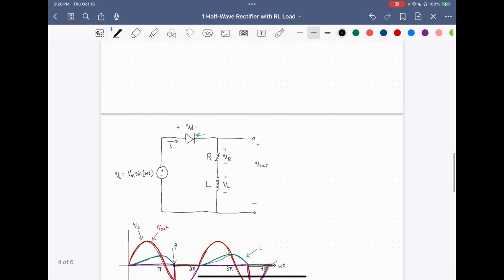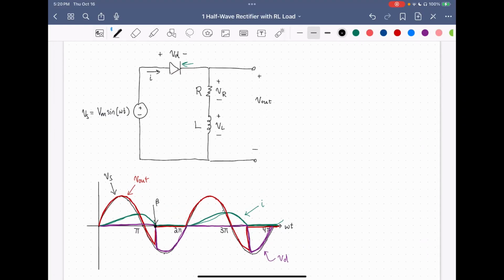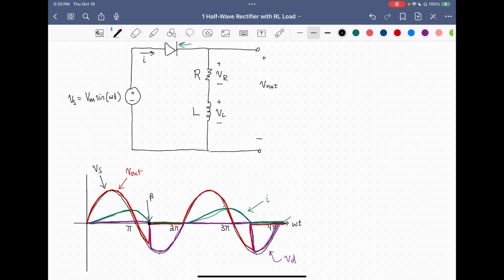So going back to the circuit we analyzed, a key takeaway is the characteristic of the diode. It's not a switch we directly control; rather the switch is controlled by the voltages and currents in the other parts of the circuit. Once the input voltage source starts to rise from 0, the diode begins to conduct. At that point, the diode's out of the picture, and it's just the voltage source, resistor, and inductor, with current flowing.